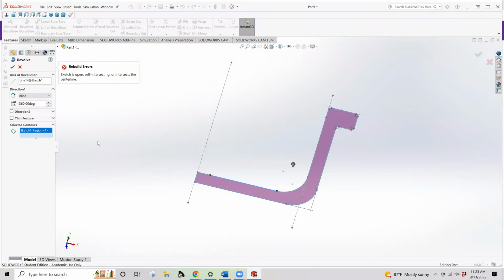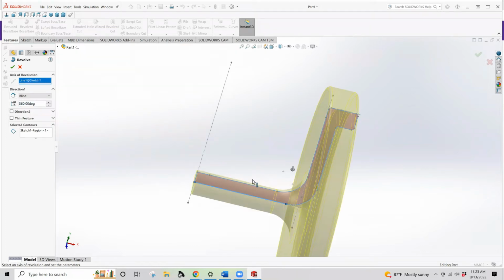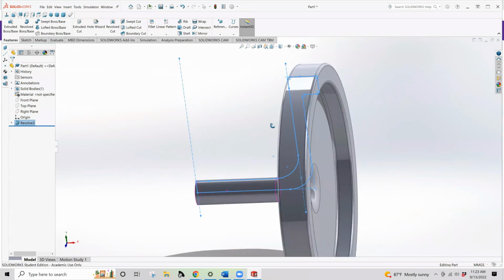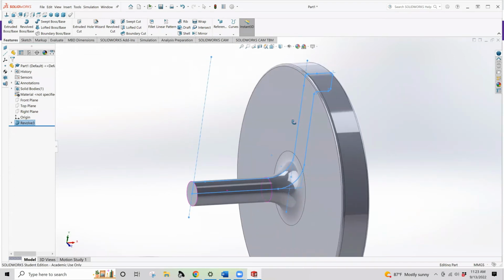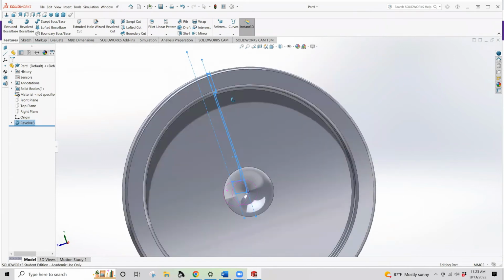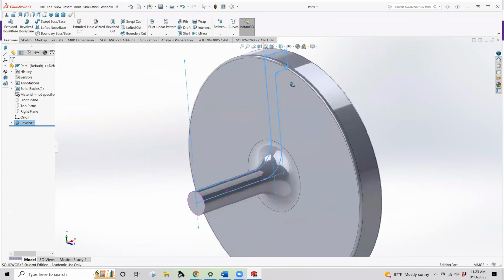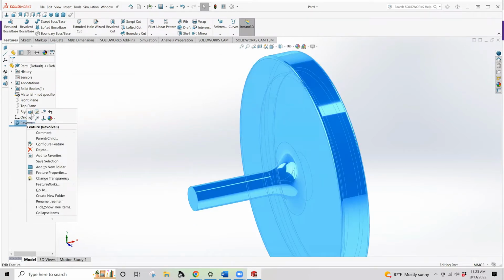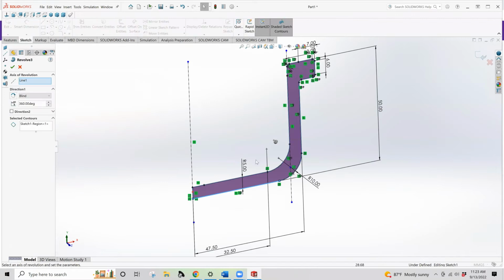In order to get that kind of revolve to work, what you instead need is you need to revolve it here where you don't have an intersecting line. So obviously this is not quite the vessel that we're going for, but just to demonstrate the point that you can get a lot of complicated geometries for a part like this, a lot of features for not a lot of work if you spend your time on the base sketch instead of some of the other details. So just something to tuck away for later when you go to do the CSWA.